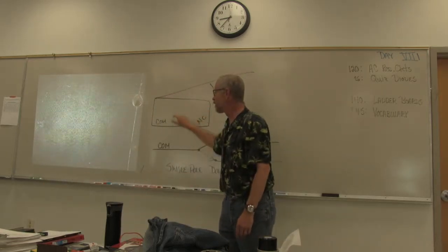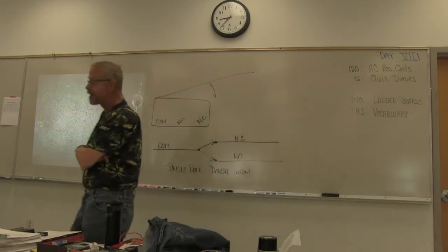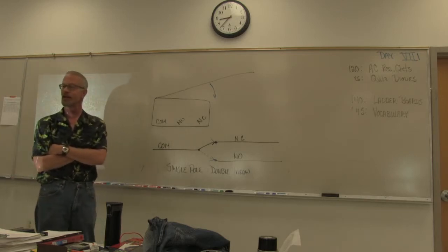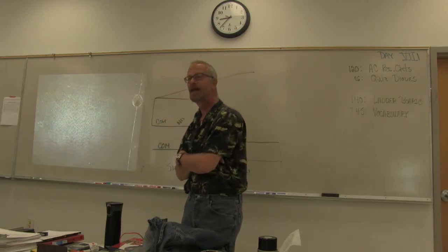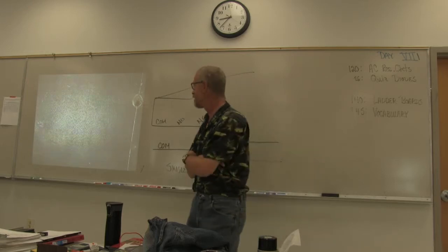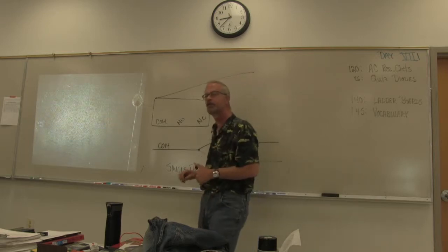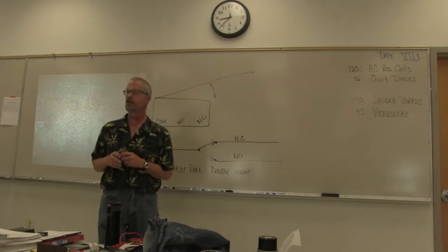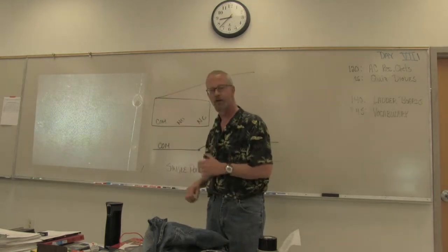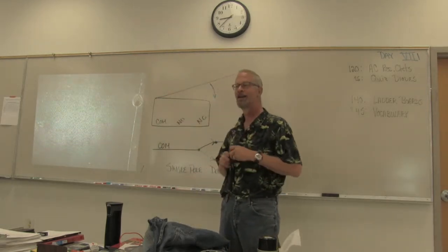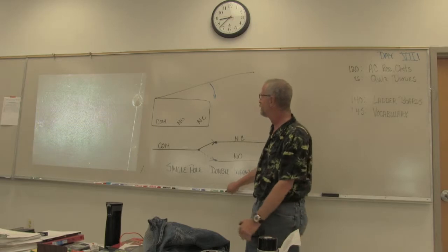Okay, what is this really for in the context of our boards? We do use these switches, but let's keep in mind that these switches actually mean a number of different things to us. I may give you an assignment that says, turn the motor on when the temperature gets to, say, 70 degrees. How are we going to model that? Well, in the real world, I'm going to have a temperature switch that is going to switch or make contact at 70 degrees. Or I may have a float switch that will make contact when the water reaches that. There was one laying around here, a nice pretty red one. When the float switch reaches a certain point, it will switch on.